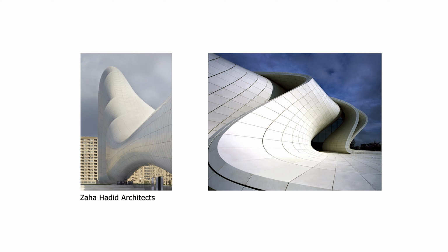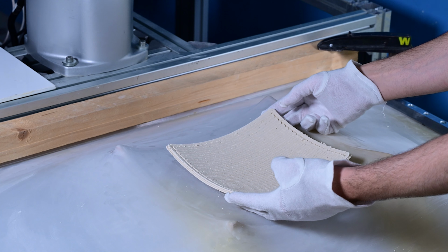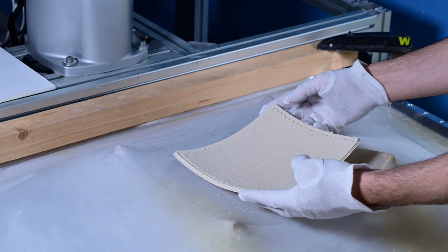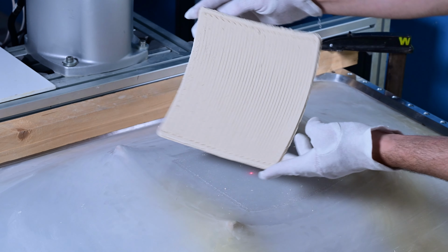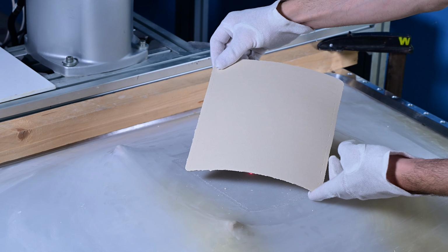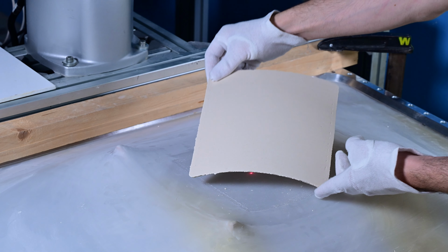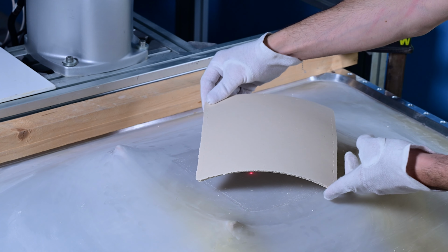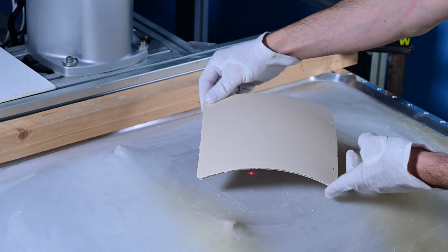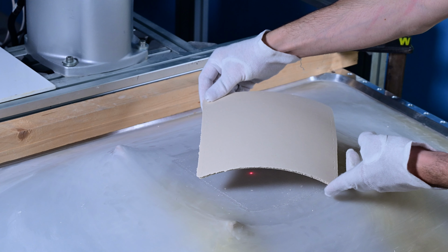Usually for each unique panel, a mold is CNC machined from a block of material. We propose molding architectural panels on a flexible silicone or rubber membrane and present a method to give the membrane the desired shape by controlling boundary conditions and air pressure. How do we find the right boundary conditions? Let us take a look at the complete design and fabrication process.